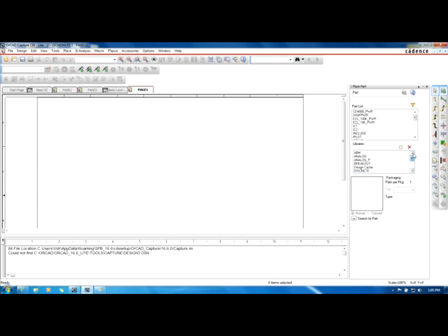So now here's something about the library. There's something a lot of people don't know, because when they lay down a schematic, they will have a problem running it in the simulator. It'll keep on coming up with errors and different messages. Some of those messages might have something to do with what part they selected, because some of these libraries aren't really meant for the simulator, and who knows who made them or what they were originally for. It might have been for another program, and it worked here too, just for the schematic part, but not necessarily the simulator. It has to have something assigned to it.